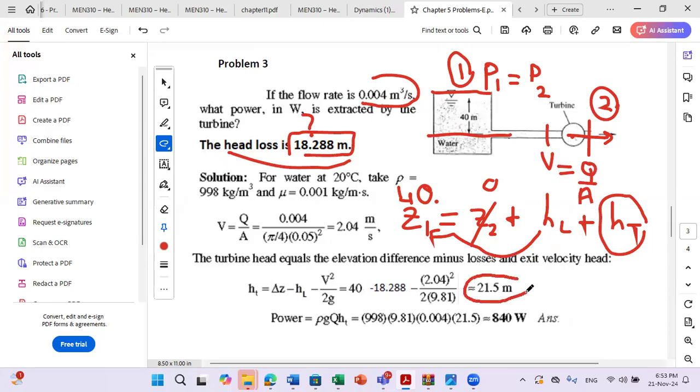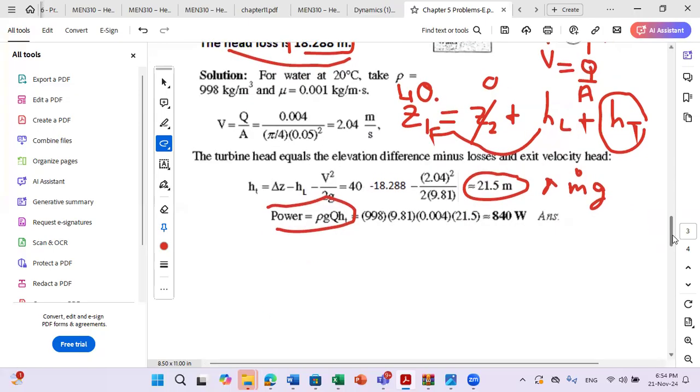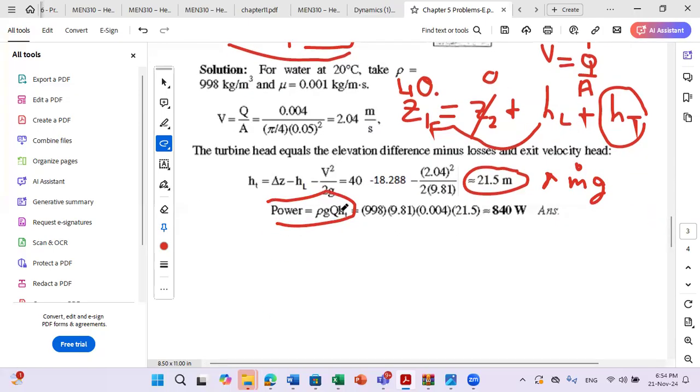And in order to get the value of power extracted from water, we just have to multiply this by m dot g. And again, this represents the useful input of our turbine. So we can take this power from the water, but the useful power actually is the electrical one. To calculate the electrical power, they should give you the efficiency of your turbine.